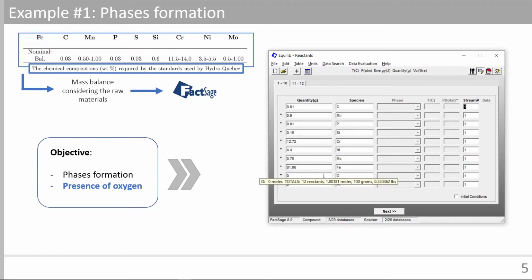As we are adding oxygen, we're going to reach the saturation limit, and depending on the condition of the operation, we can either form a slag, a spinel, or maybe it could be in equilibrium with the gas. So this is one of the aspects of the project. So what is the phase that saturates them out and limits the amount of oxygen that we can dissolve in the liquid alloy? I'm going to try to evaluate that using the alpha parameter.